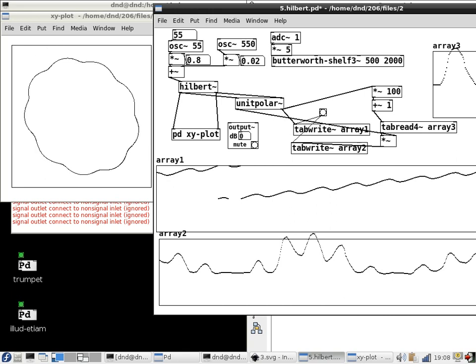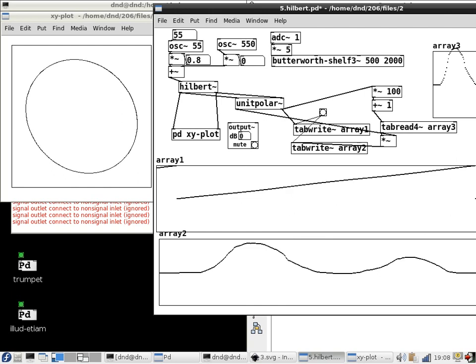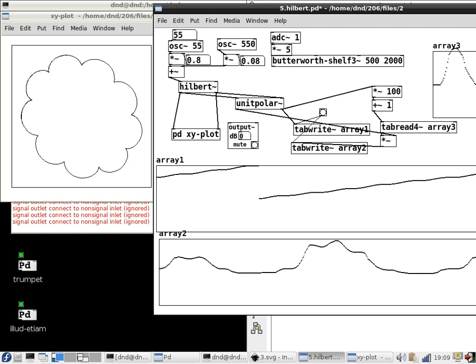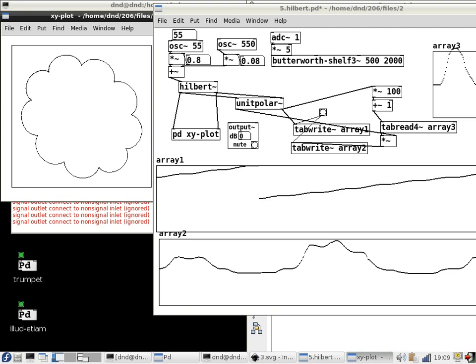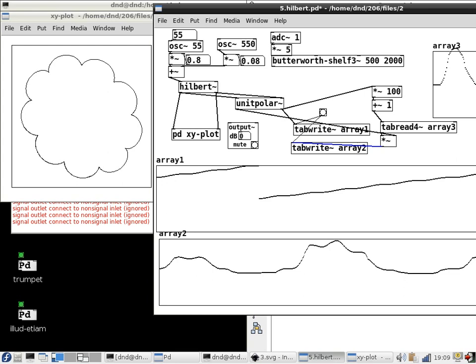Let's drop this down and see if I can actually believe that this is the original signal. Okay, there it is. But then this peak is narrow enough, apparently, that it becomes easy to wiggle past the peak and make the peak, whatever you call it, trifurcate, turn into 3 peaks, forward, backward, and forward. Yeah, there. Oh, actually, another thing's happening, which is more important than that, which is this. 2 things are changing here. One is the phase is getting modulated like that, but the other is that the amplitude is getting modulated too. So here's now the amplitude modulation.